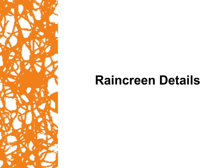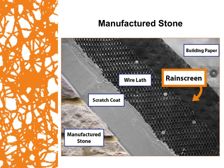Rainscreen details. Looking at the picture in front of you, you'll see that it is a manufactured stone cutaway, where it's showing the building paper being a 60-minute or greater building paper, the drainage mat or Rainscreen, the wire lath, the scratch coat, and then manufactured stone. This would be the same cutaway if it was stucco, just replacing the manufactured stone portion with your stucco layer.